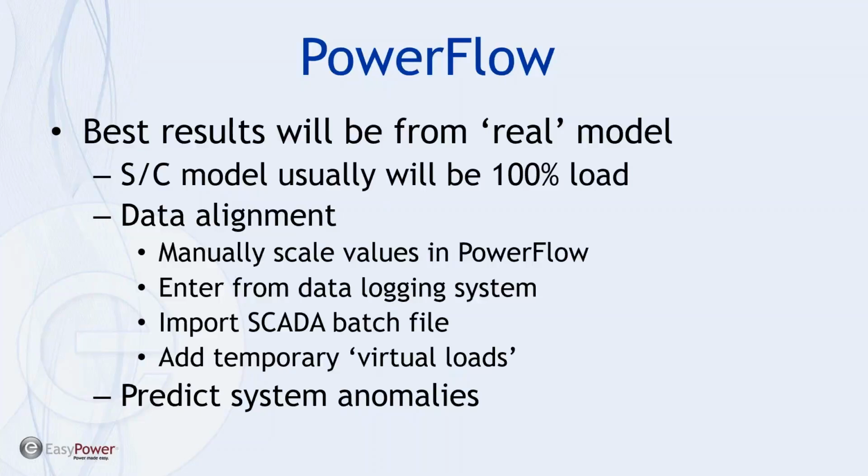So there's a need to have data alignment, and primarily this can be done in EasyPower one of three ways. You can manually scale groups of loads or individual loads in the PowerFlow tool itself, or you can enter the data that you've collected with data logging equipment, which often can be portable, or in some cases you can import SCADA data if that's something that you have access to. And frankly, it takes a little bit of effort. It's not just one size fits all, but it's a way to save time as far as this